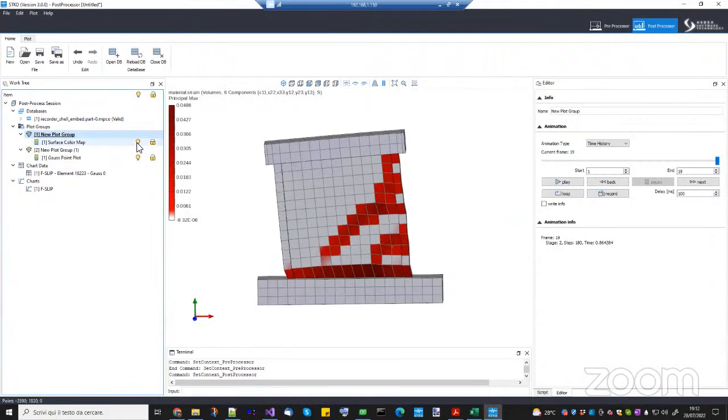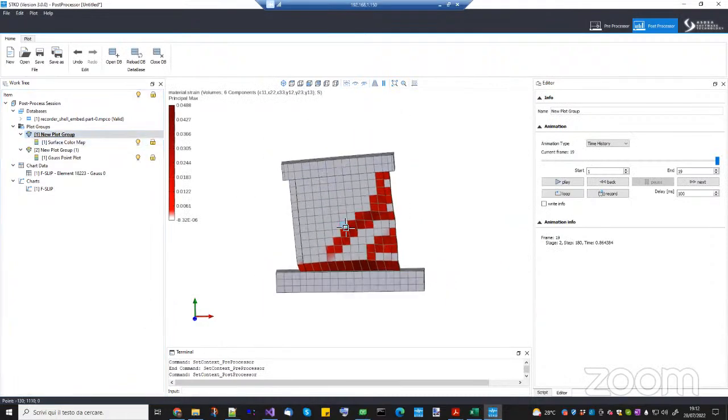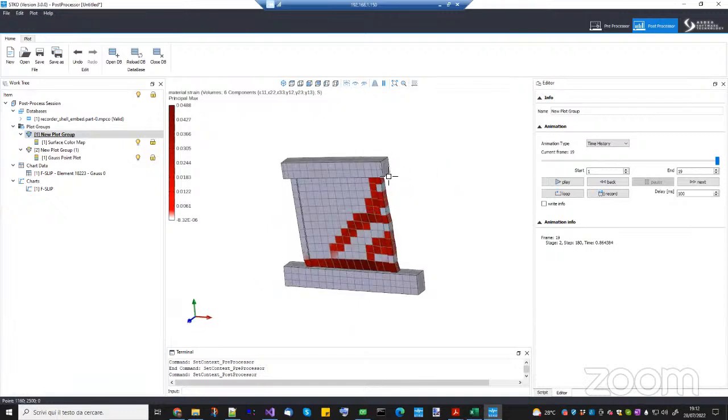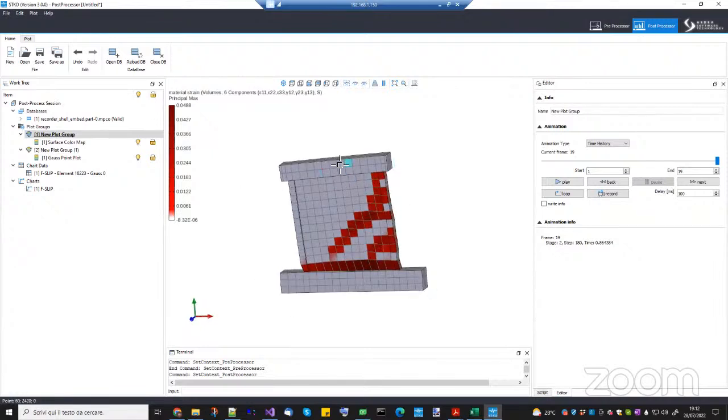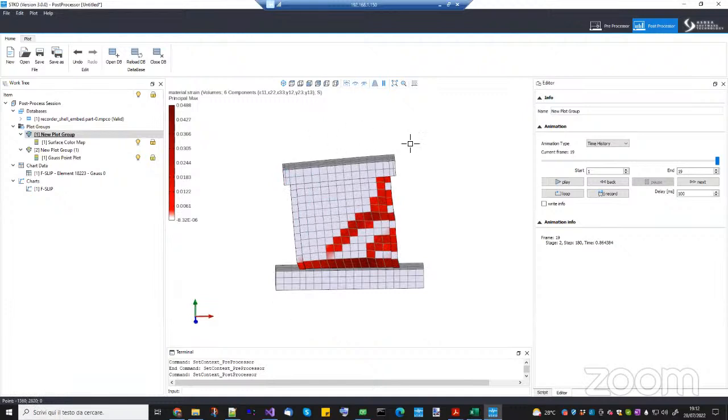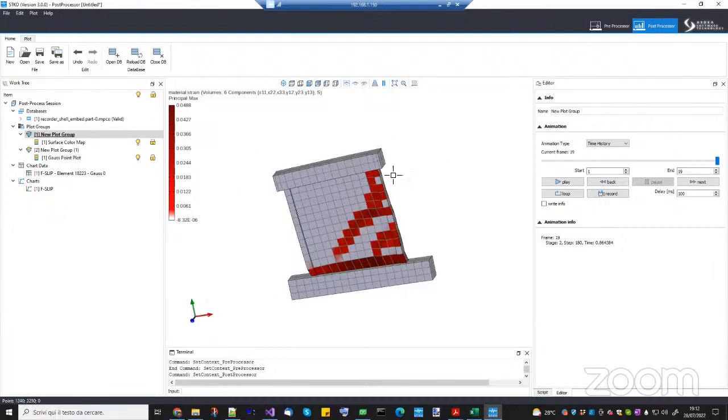And then one last thing I want to show you today is what Lin Sun was asking me yesterday. How do we apply cyclic loading? Because actually this model is very sensitive, because this is a shear wall subject to a cantilever kind of boundary condition. And since it is a squat wall, but actually it's a square wall, it is something in between the bending failure and the shear failure. So it is very sensitive to the location of the applied load.